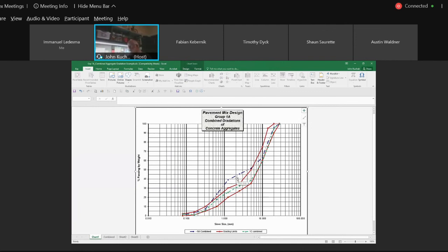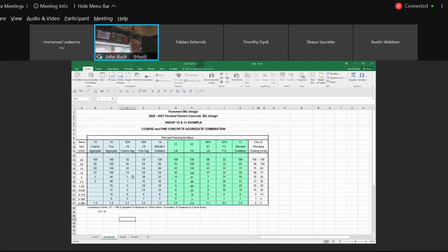And if you're in a floor slab, you may have a mix where you have almost a 50-50, or maybe 55-45, because now you're looking for workability. You're looking for a fatty concrete mix that's very putty, easy to finish. Pavements are a little different. You're using different screeding operations. You're using vibrators and finishing. So that's kind of where you can start. If you don't even know where to start, you can say, I'll go 50-50. Oh, obviously I've got too much fines, so I'm going to go 55-45.